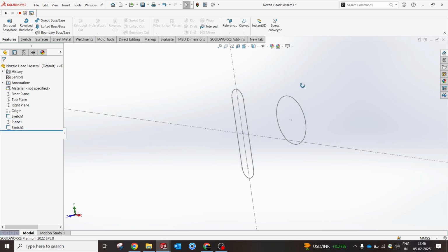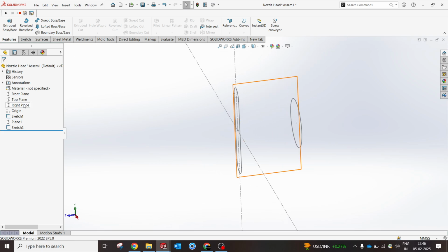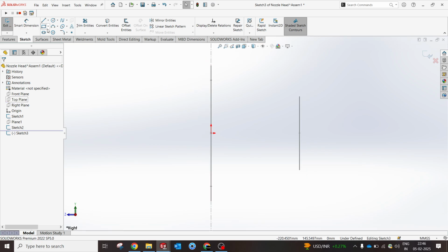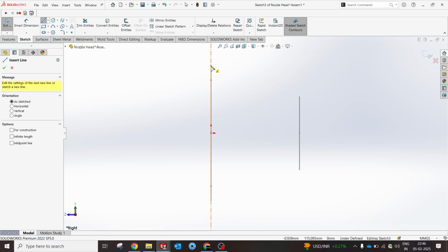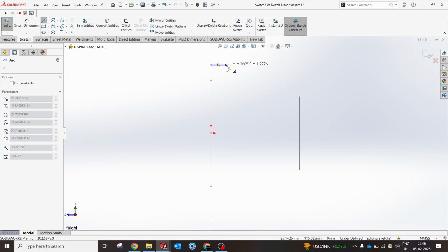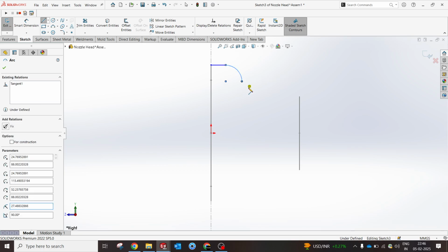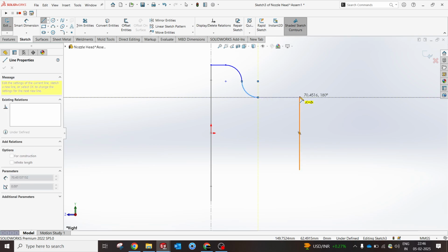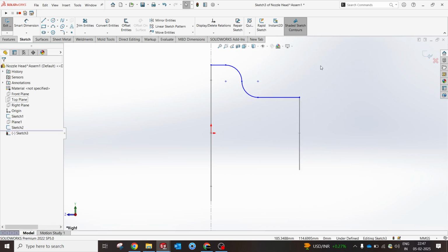decide our shape. So what I will do, I'm gonna select now on the right plane. Yep. So this time I will just create a guide curve. So I'm just gonna draw, I've selected the line. From here I'm gonna just draw approximately a line. Again, if you draw back, I mean come back without removing or pressing escape, you will find an arc. Again, just make sure you will be having another arc and go for the line. Yes, perfect. So now you can decide how you want.